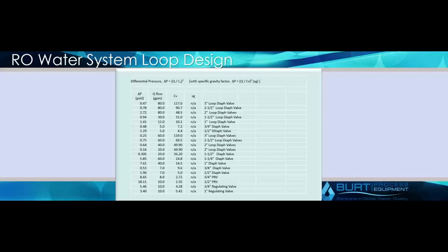If you have a system where you may be in excess of 150, at your actual pumps, in excess of say 135 psi, you may have to put in a secondary pressure system in your system. What I mean by that is, if you're flowing at a higher rate, you may need to put a drop off of your loop to another basically booster distribution, kind of polishing system in those cases. That's not very uncommon.